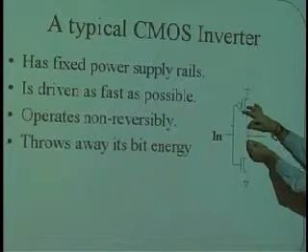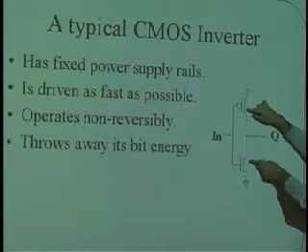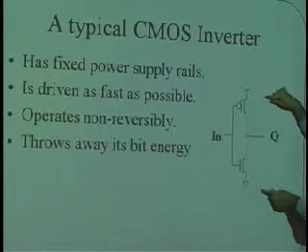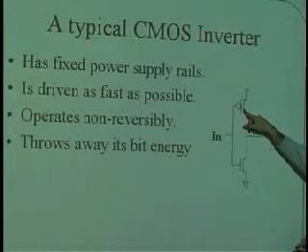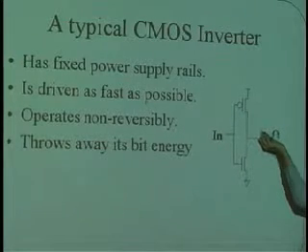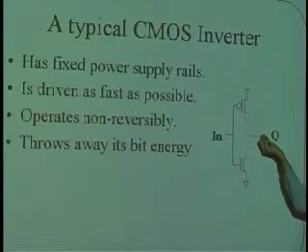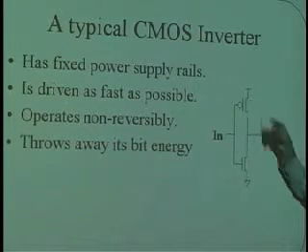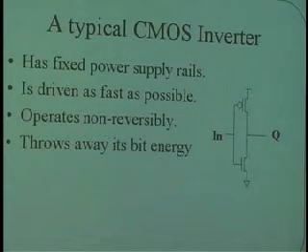And then we're going to very slowly let the voltages on the top and the bottom go from 2.5 volts up to 5 volts. Very, very slowly. And this turned on switch will slowly charge the capacitor, but it will charge it in a recoverable way without allowing the resistance to ever get in the way. So maybe I can draw it over here a little better.